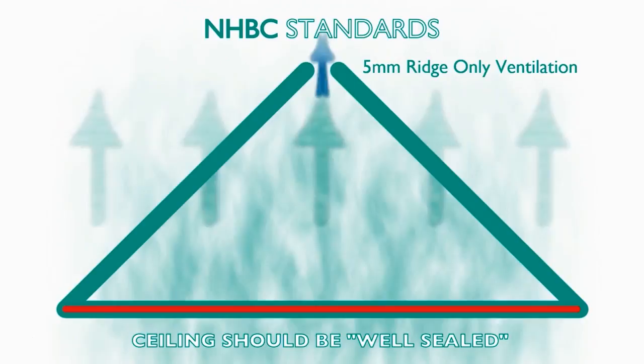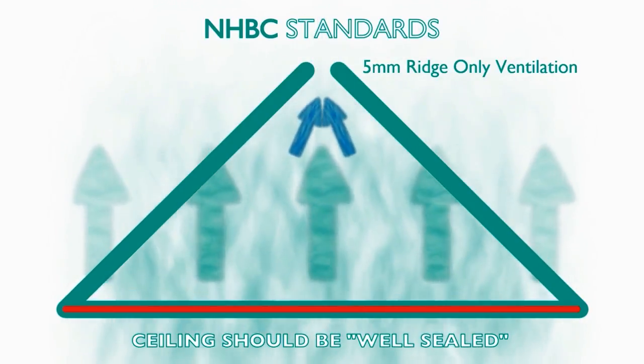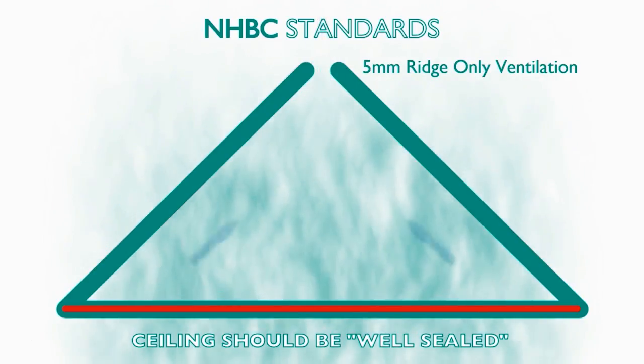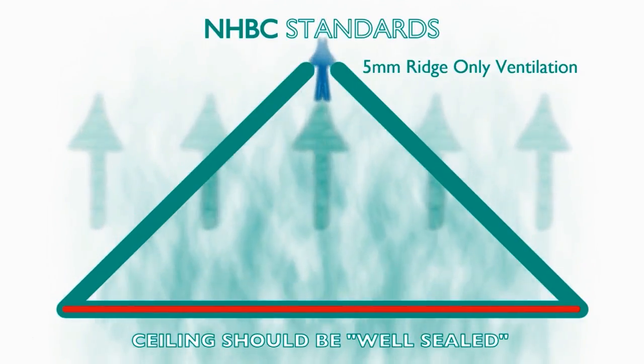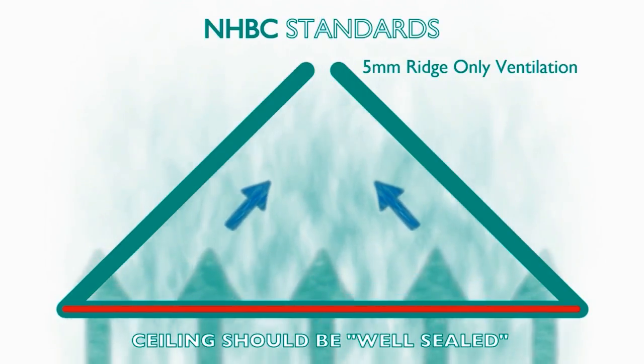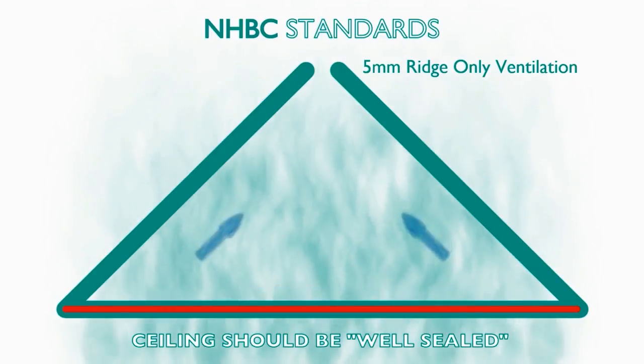Aside from obvious requirements like not having any gaps or cracks in the ceiling, this standard sets air leakage requirements for hatches and downlighters and requires sealing of service penetrations using suitable proprietary products, all of which can complicate the design and construction process and potentially introduce unforeseen costs and delays.